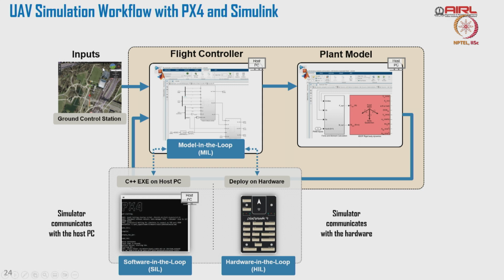Based on a specific application, you are planning the whole mission, and the entire mission is planned. You just say I wanted to take off at one particular latitude, longitude, and go to a specific height and move from point A to point B and point C and deliver something and return back. So once you plan the mission, you are connecting the mission to your flight controller. The flight controller now has the entire mission, right. Now this is where the initial connection takes place.